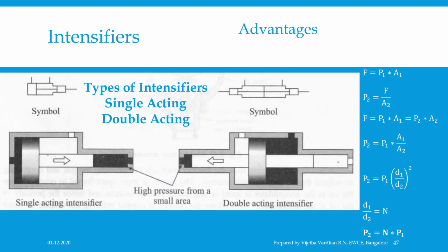And then what are the advantages of this? It gives a higher performance and longer life on account of lower operating pressure, a more compact system, greater safety due to low pressure in general, and ease and accuracy of control. Multiplication of force can happen, and it can be easily started, stopped, speeded up and slowed down with the help of a simple lever operation provided in the circuit. And coming to the applications: hydraulic work holding, pressure die casting, starting and impulse testing equipment, hydraulic power packs, riveting and so on.